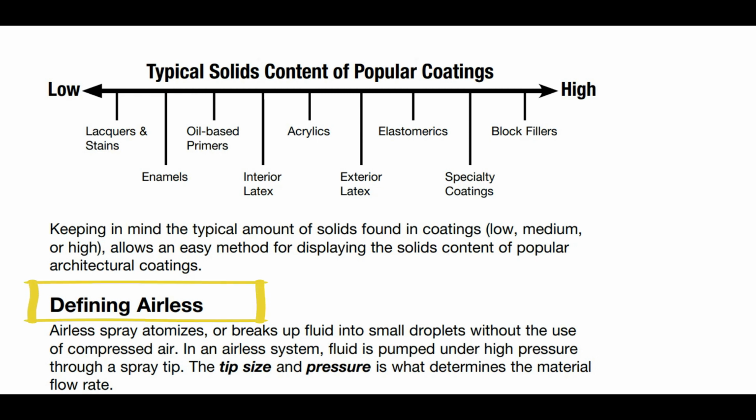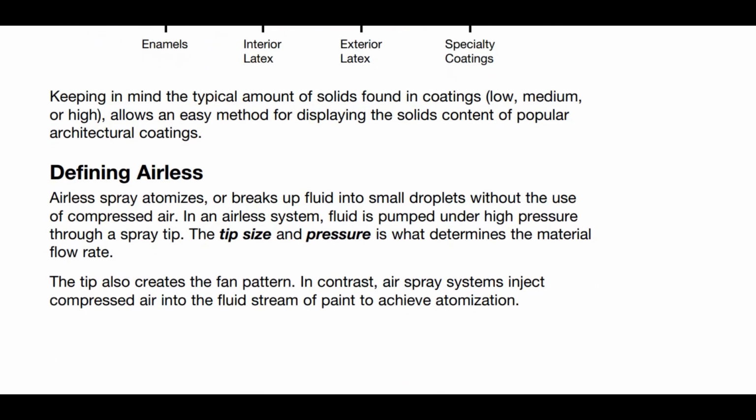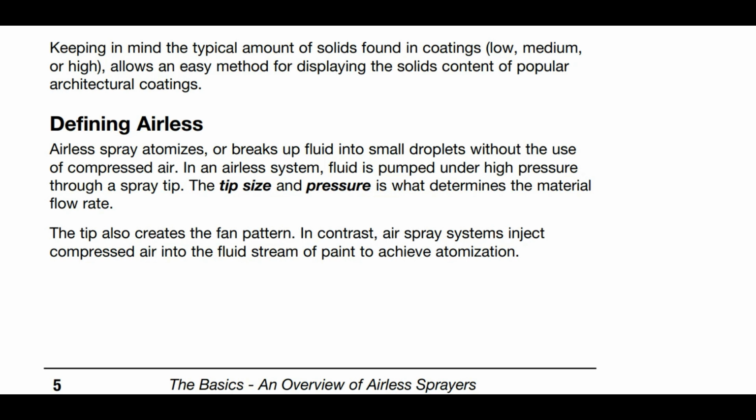Defining airless. Airless spray atomizes or breaks up fluids into small droplets without the use of compressed air. In the airless system, fluid is pumped under high pressure through a spray tip. Tip size and pressure determine the material flow rate. The tip also creates the fan pattern.